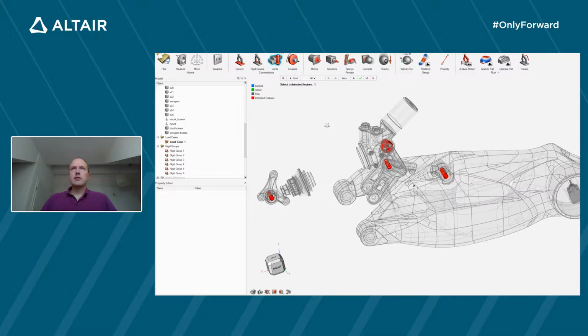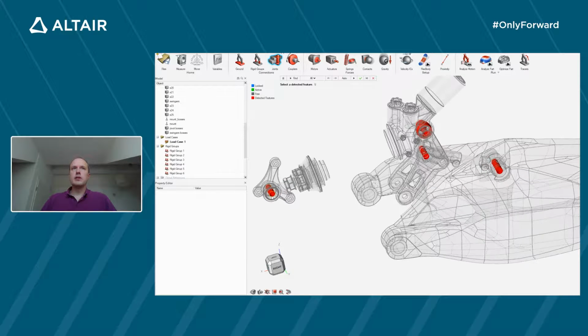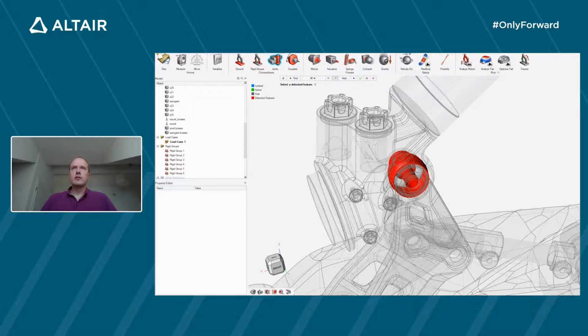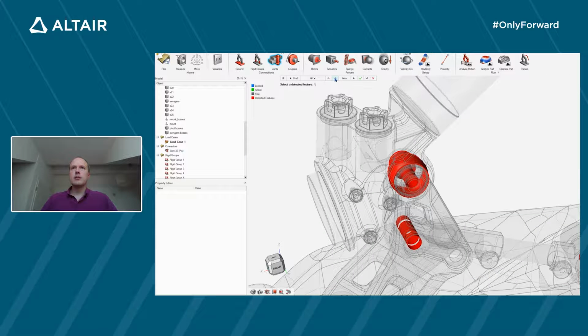Okay, what it found here is first the aligned holes of my structure. You can, for example, zoom in or use the arrows here to isolate the different found holes here, and then click on the ones that were found. Choose a sort of connection, in that case a rotating pin, that should describe the relation of the two parts here, and then go to the next one and for example define the next rotating or other joint.